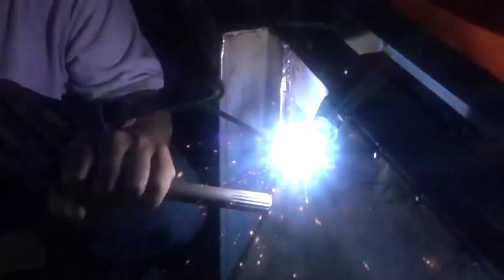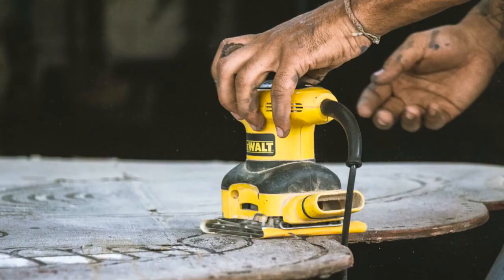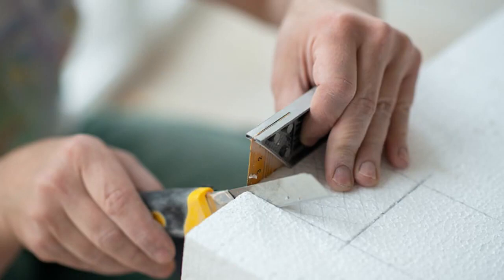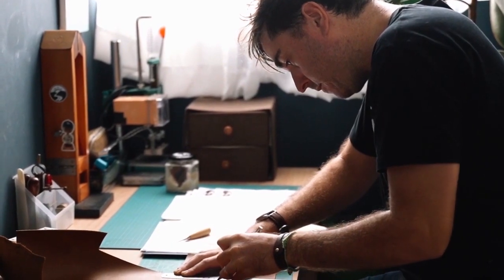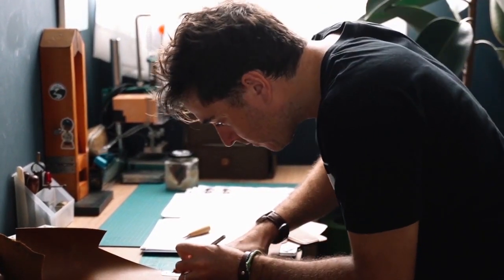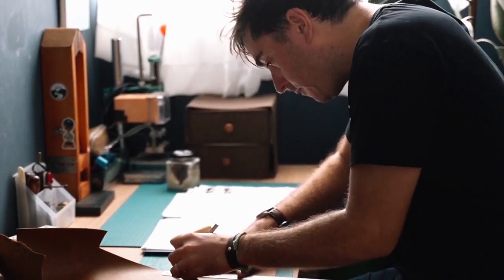When all the legs are connected to one another, the base plate that connects to the wood of the seat to the legs should be welded on. Then we should cut the correct size pieces of the chipboard for the base of the seat. By using a router, you will get an accurate and clean cut. The foam should then also be cut to size with a sharp blade. After the foam has been cut, the leather should be precisely measured and cut with a blade to ensure that the covering of the foam would not cause any wrinkles or folds.